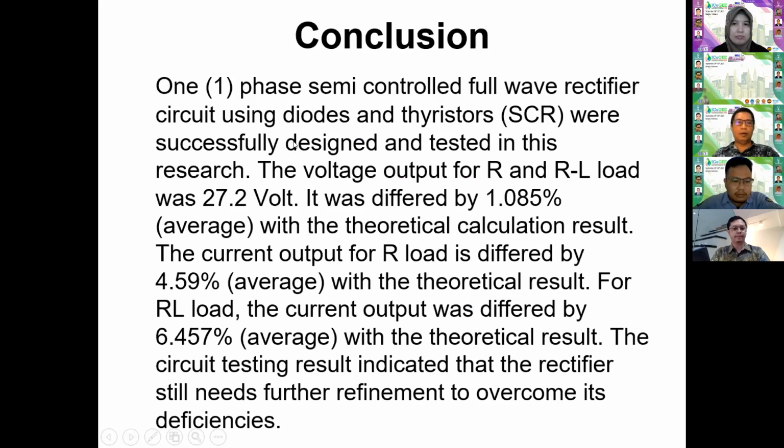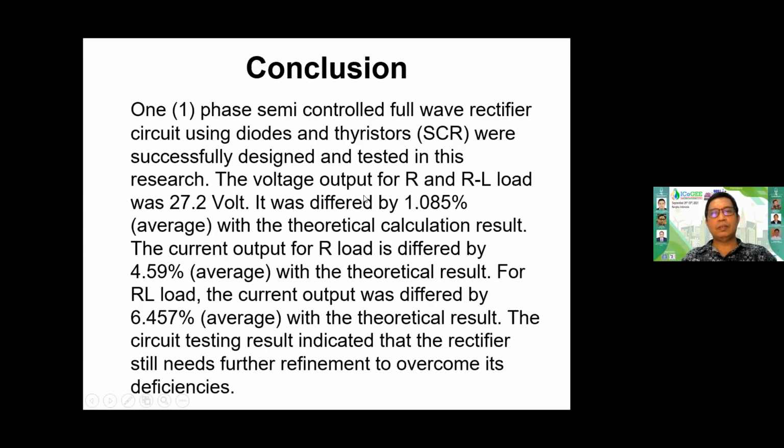Conclusion: one phase semi-controlled full wave rectifier circuit using diodes and thyristors (SCRs) was successfully designed and tested in this research. The voltage output for R and RL load was 27.2 volt. It differed by 1.085% average from the theoretical calculation result.